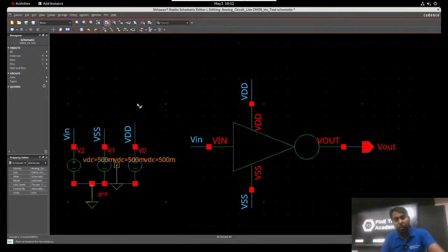But of course, before going to the tool you must have an analysis. If you try directly on a tool, you don't know anything, you just provide the supply and the tool provides some output. If you give the input, the tool will provide the output. But if you have an understanding that PMOS is charging and NMOS is discharging, how it will increase and how it will decrease, it will increase your information and your performance also.